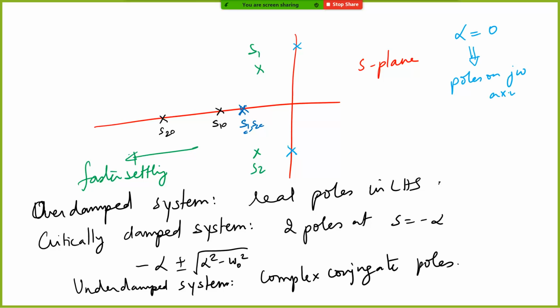The reason that I mentioned this to you is that many times you may not have an RLC circuit to talk about underdamped, critically damped, or overdamped response. You might get this kind of second order behavior even with your normal circuits where there are transistors, resistors and capacitors.